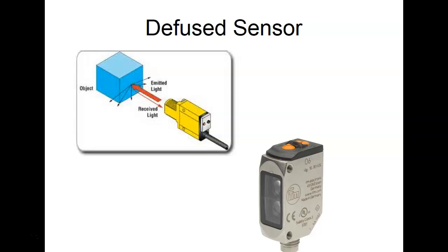We'd have to make sure that we detect properly. It doesn't mean it can't detect objects that we call black, because there's no such thing that I know of as perfect black. Black reflects a little bit of light, but it would have to be extremely close to the sensor. The lighter it is, we could have it further away, right? Does that make sense? So that would be the only problem with it. We have several of these on the manufacturing lines over there.